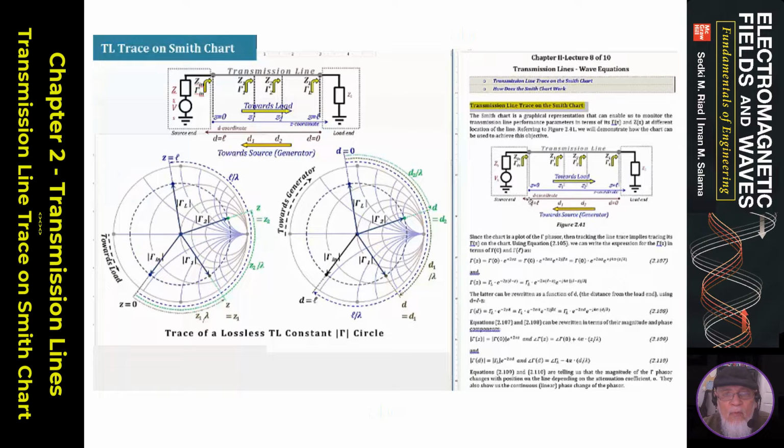and would be equal to L at the source end. I'm going to assume a couple of locations on the line, Z1 and Z2. At each of these locations, I'm going to label the complex reflection coefficient gamma 1 and gamma 2, and the driving point impedance at this location here would be Z1 and Z2. Always use the driving point impedance expression assuming that we are looking from the source towards the load side.